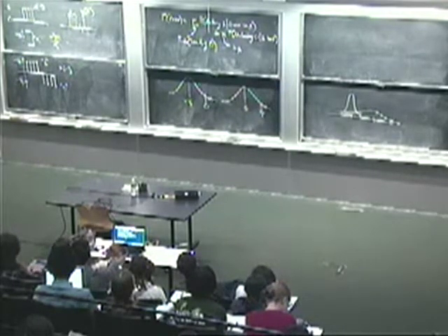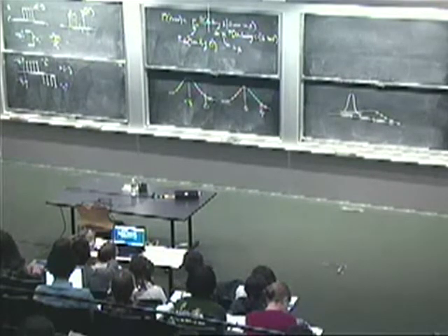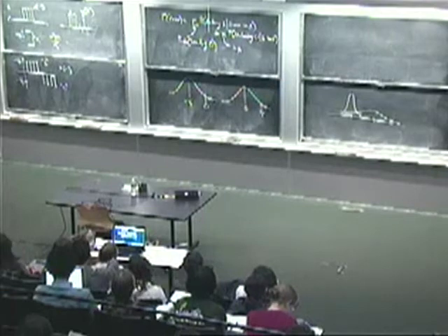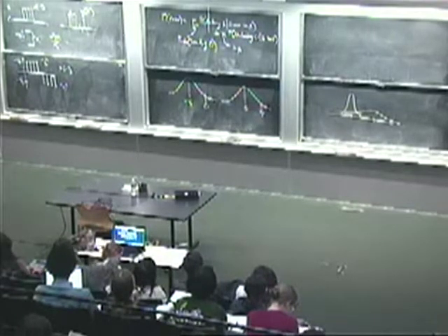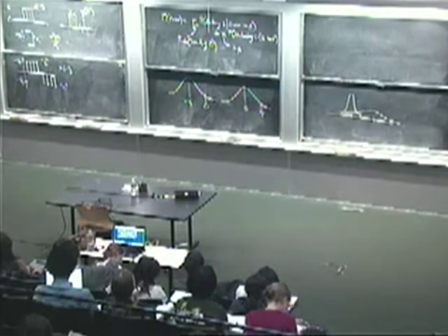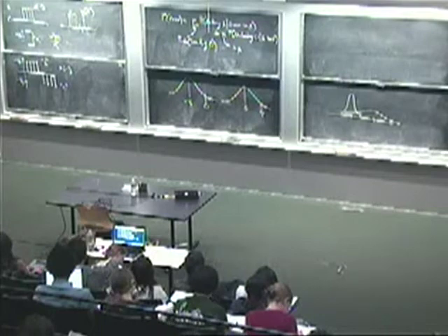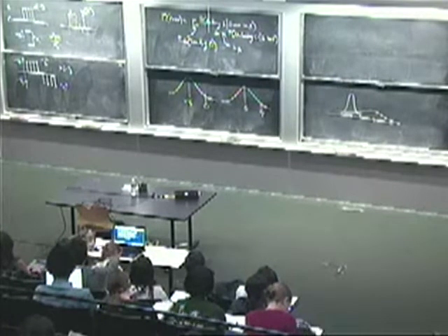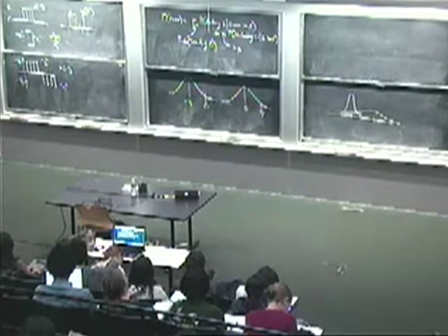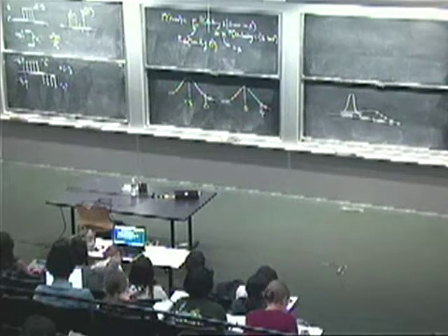Now, this is not an integral you can evaluate in closed form. It is a tabulated integral, tabulated most conveniently in terms of something called the error function. And so when you work through the calculus, and I won't show it to you here, it's in the book, you might do it in recitation, you discover that the probability of error is this error function of square root of ES over N0. N0 is notation for 2 sigma squared.